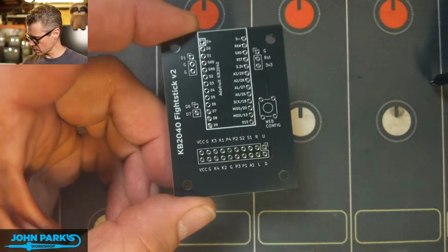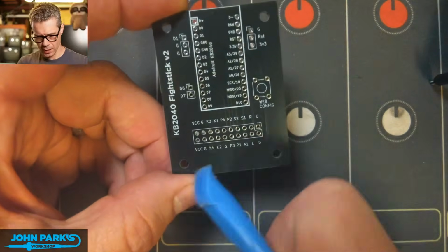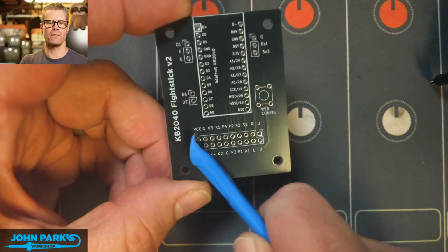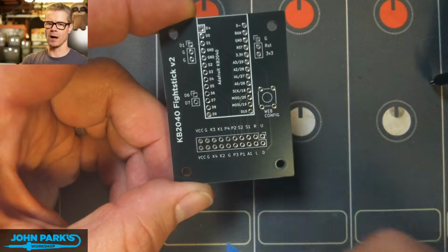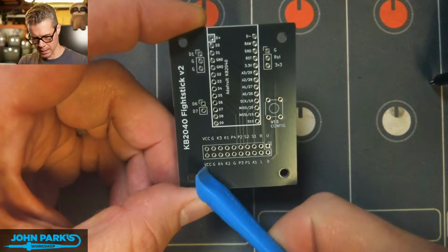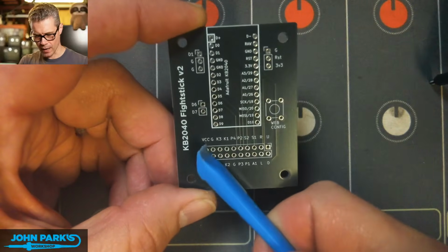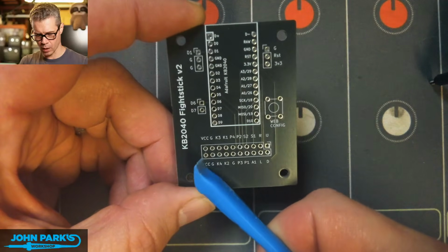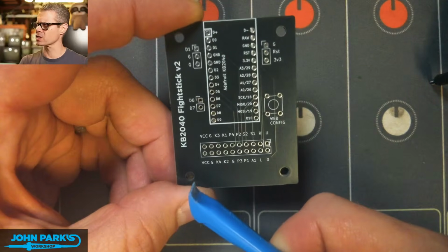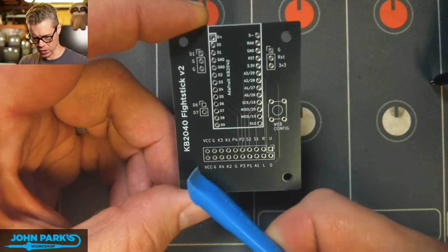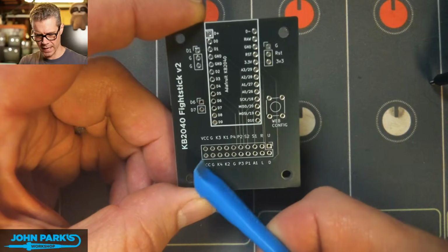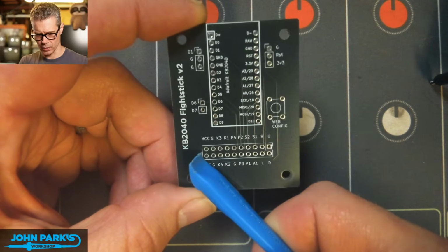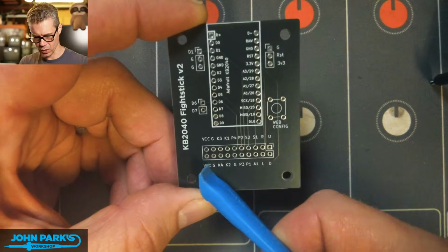And as I mentioned, these will often leave out this first two set of pins. In fact, the harness cable that I have does not have wires there because these two are used for, I think, some optical joysticks only, so they're pretty uncommon. So I may revise this with those not connected and then give you a little solder pad to connect if you want to use those.